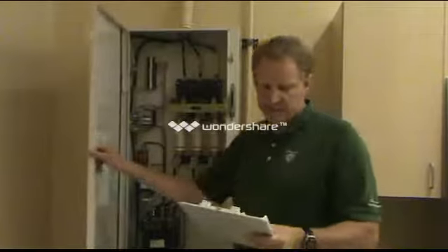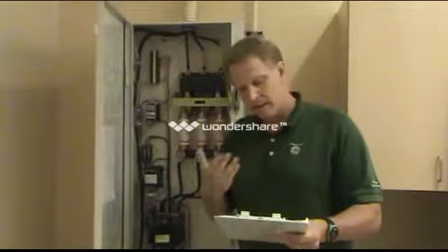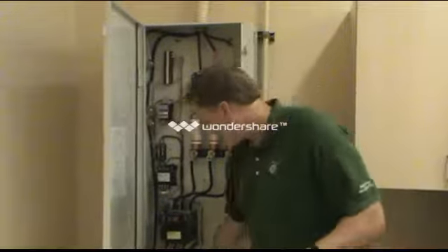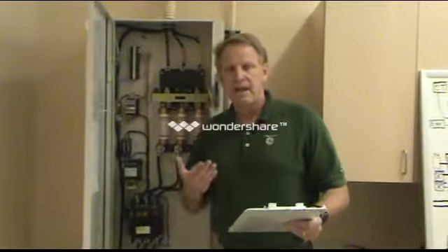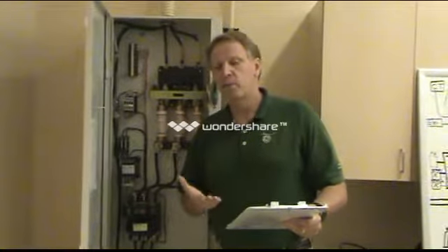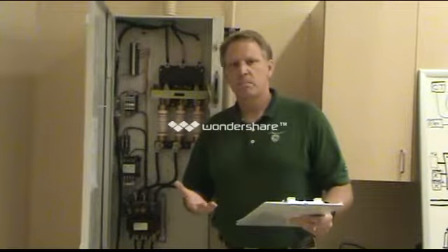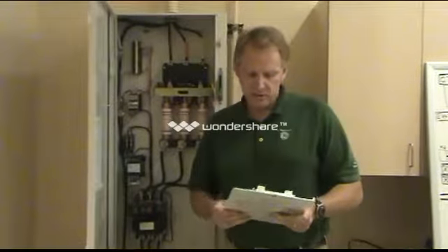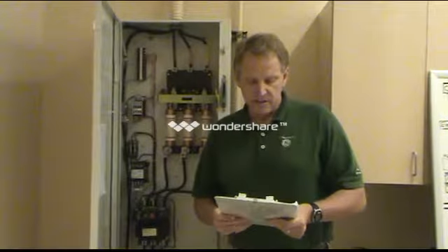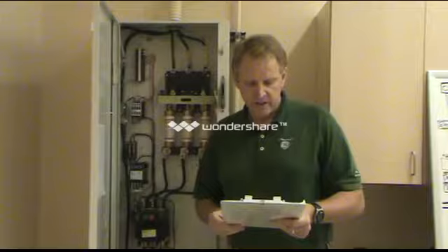Okay, is the ground run inside the same conduit as the feeders? This is an important question. So make sure your ground is run inside here, not run separate. If it is run separate, that's an NEC violation. Actually, the impedances get very high, and if we're running high current through there, it ends up looking like a toaster. It can burn up the conductors, cause heating issues, possible fire damage. So it's an NEC requirement.